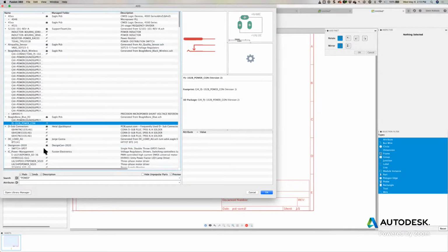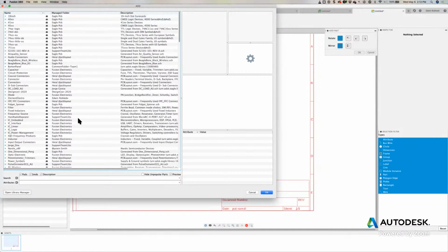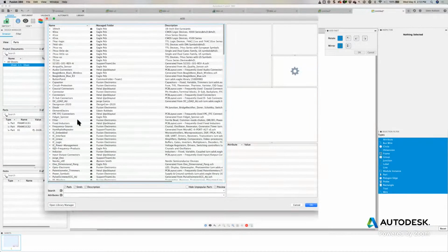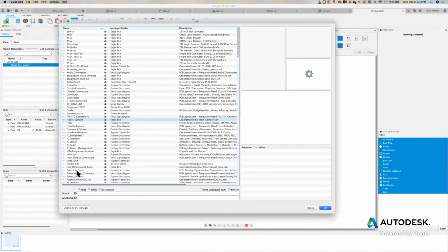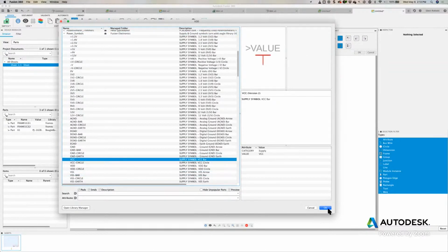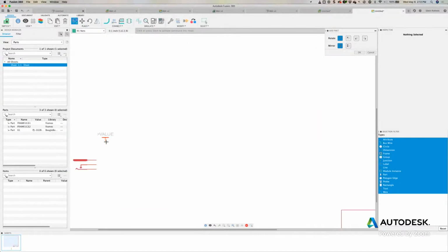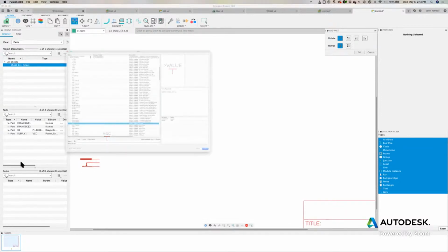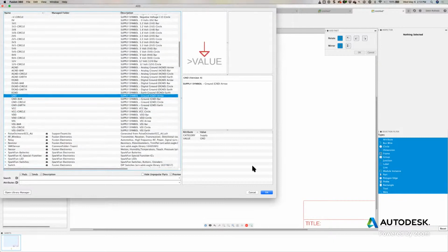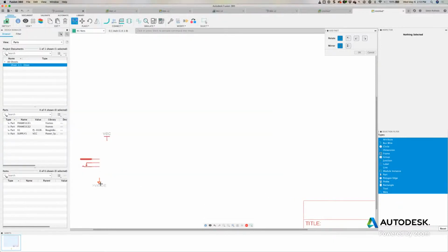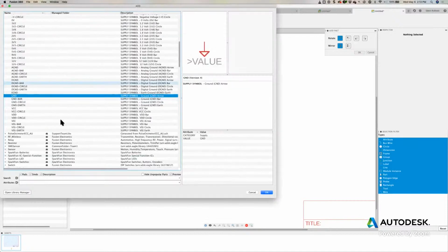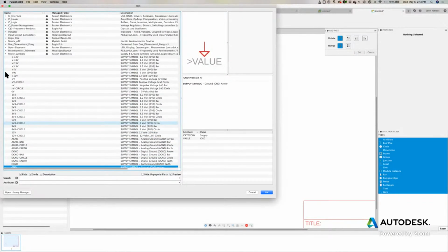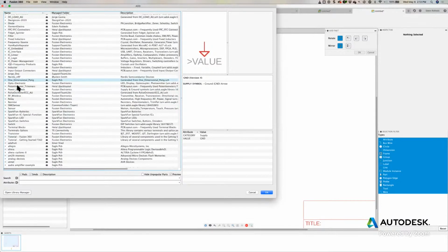Now I'm going to go ahead and find my power connections here. I'm going to be using my VCC right here. I'll go ahead and place that right here on top. Okay, hit escape, and I'm going to go get some of my ground as well. I'll put 2 grounds down. So one is going to go here, and the other one is going to go here as well. It's my ground. And I just need one capacitor, which is going to act like a filter. So let me go to the capacitor library.